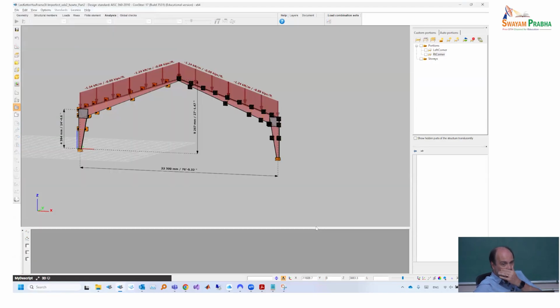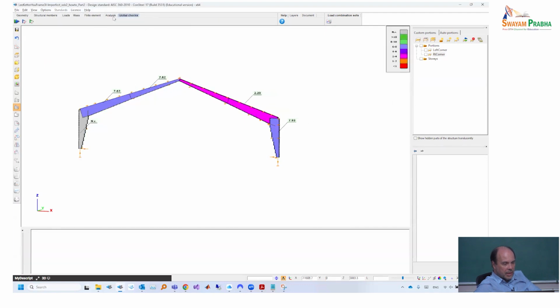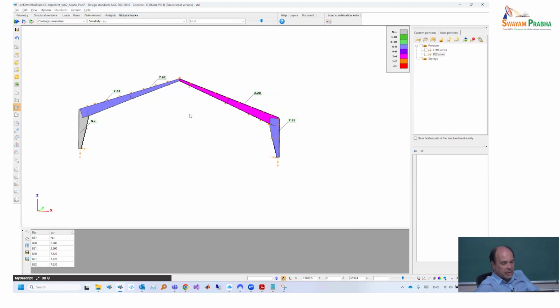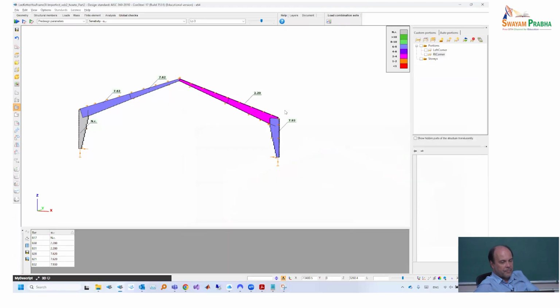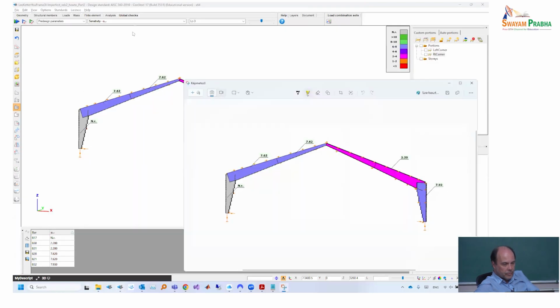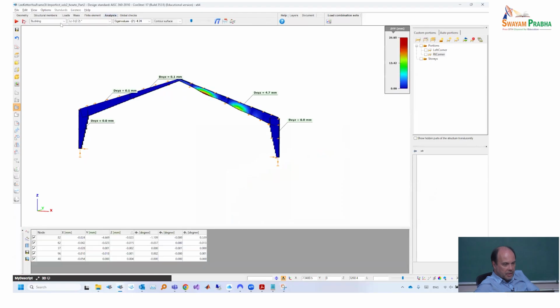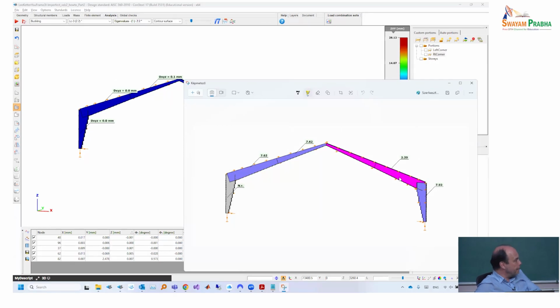Now I calculate only load combination 3 to make sure. Okay, so this is my map. I come back to analysis, buckling, load combination 3. So generally your map has different values at different points that correspond to different load combinations, a bit misleading. That gives some sort of, if it's run for one combination only, then it works well. Then it really gives, from that given combination, which mode was assigned to which members. Once you run it for more combinations, what it shows starts to be a mess.